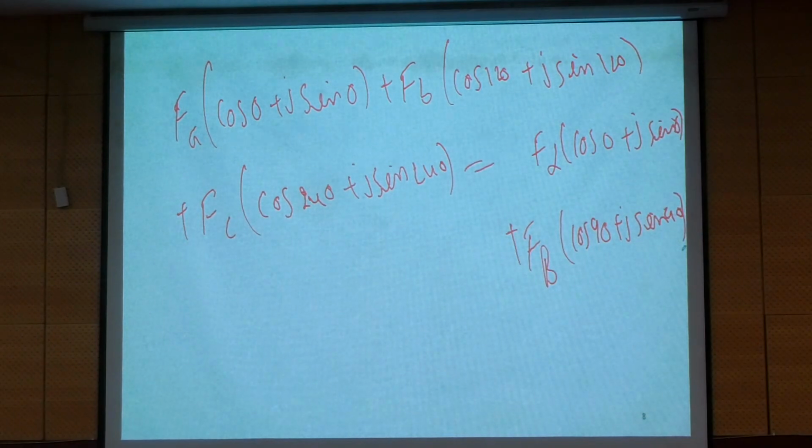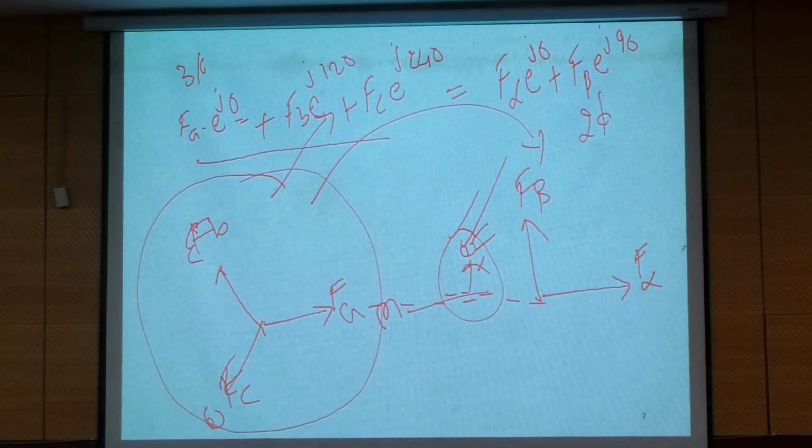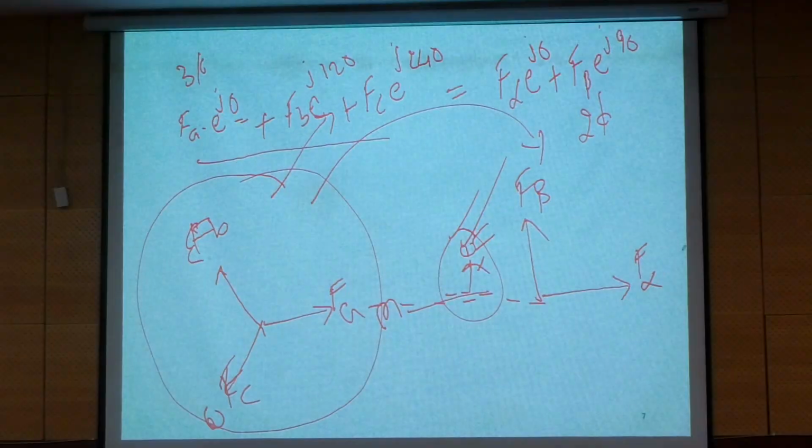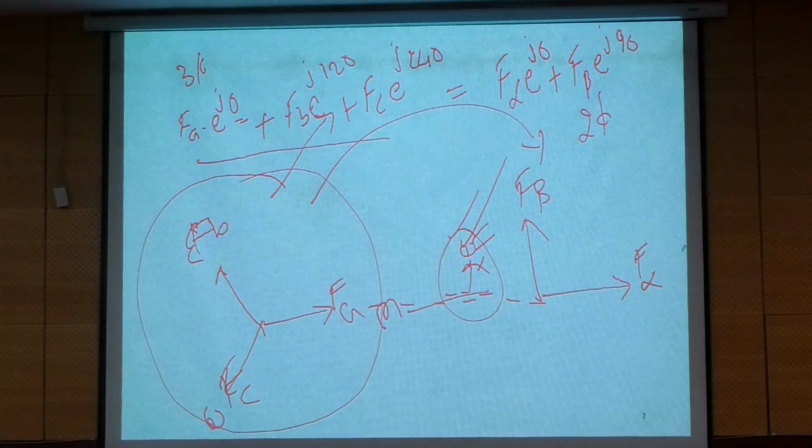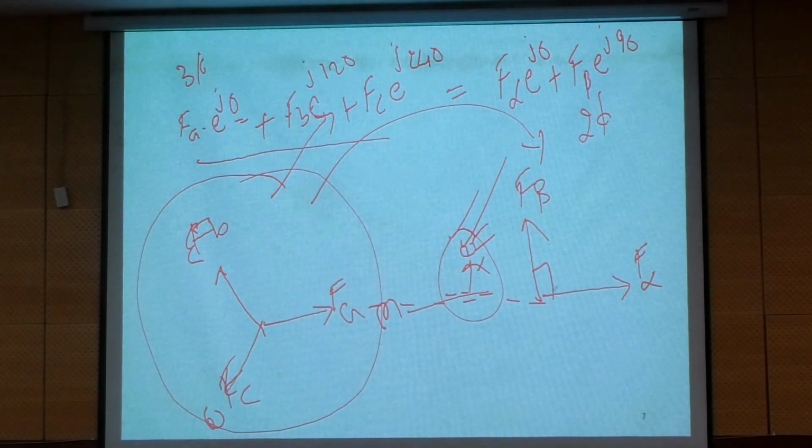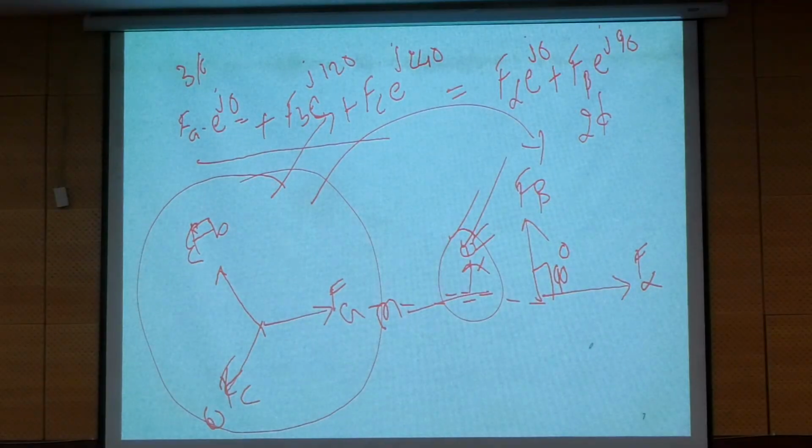What is the advantage here? Tell me. One more important thing is that F alpha, F beta are under your control. Practically, these two components do not exist in the actual system. You got my point? But without losing properties, from a control point of view, we can convert the three-phase variables into two-phase. While converting the variables from three-phase to two-phase, if you take the space displacement angle between these two as 90 degrees, what is the advantage from a control point of view?